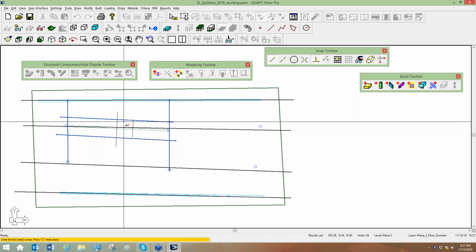So this section, I can call it section A, for example. The section has a flange width, it has a stem width, it has reinforcement that you assign to it as base reinforcement, and the program allows the user to use this modularized approach to beam design and detailing as a kind of a standalone wizard built inside of the program, and it's going to allow you to handle the beam design more cleanly versus how we do it now.